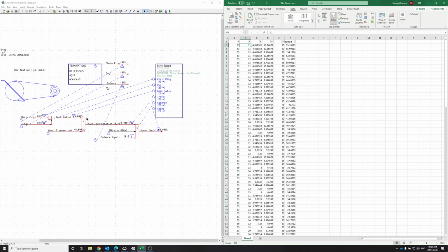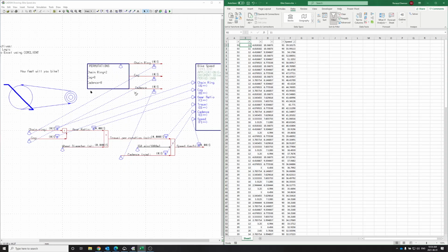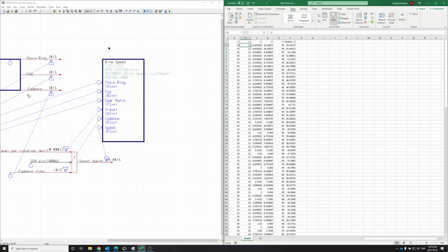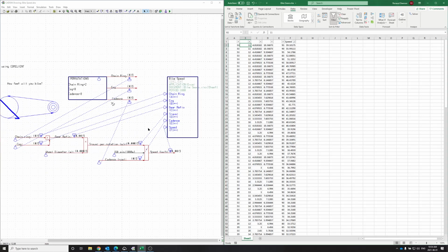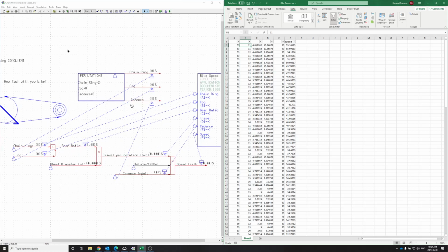Here we've, to summarize, learned how to use signal logic, some divide, multipliers, how to name signal lines, how to format them, how to equate stuff to other variables. We've also covered how to add a COM client that'll communicate with Excel, from CADSIM to Excel, and vice versa. You can pull data from Excel into CADSIM. That'll be something we'll try in a different tutorial. And finally, we learned how to use the permutations module over here.